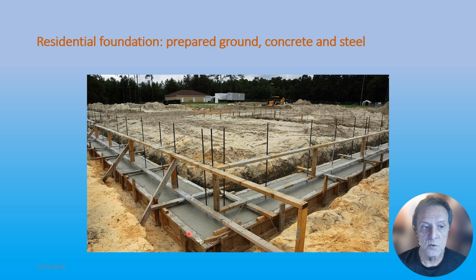So you have a simple perimeter strip footing filled with wooden forms, and you have concrete filling those wooden forms. And importantly, reinforcement. Here you have vertical reinforcement, which ties the footing to the structure itself, and invisible, but most likely within the concrete, there is more rebar to reinforce the concrete once it attains maximum strength.